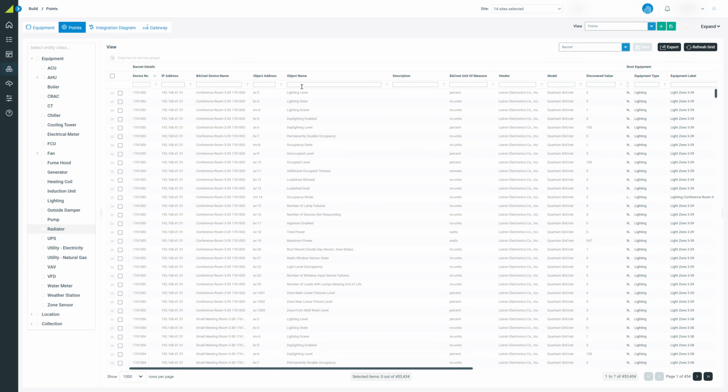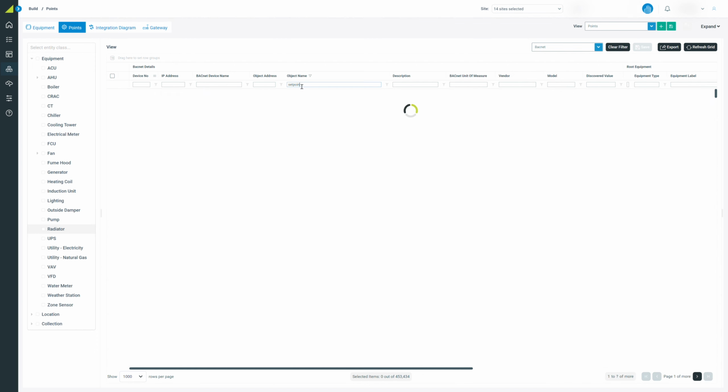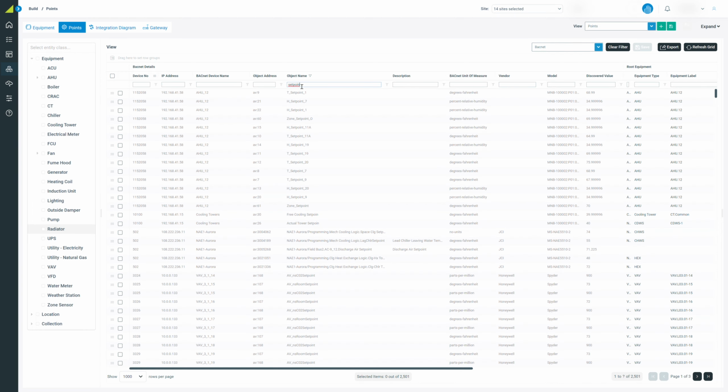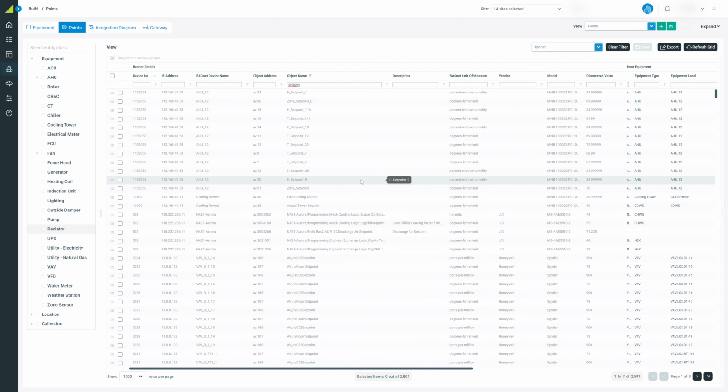But just to get into some of the specifics, set point is a classic. If I look up how many different set point names there are, you'll see here that to do any analysis on temperature set points that might be out of range, you need to be able to persistently call it a set point, irrespective of how we're getting it in. But we do maintain and keep the original name, because the vendors who need to potentially fix, repair, or configure these, this is how generally they'll know it, because it's in the controller like this.